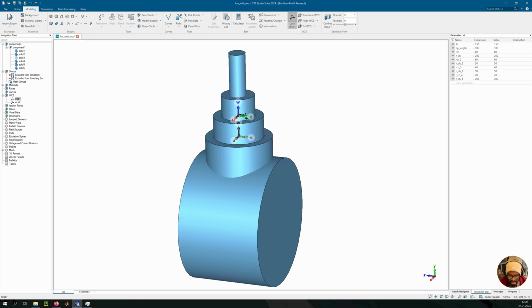So it's starting from the WCS2 because that's the latest world coordinate system, I think. I'll just call it WCS because I'm not sure about the name. So it's starting from the latest WCS because that's the last we used, so it's still recording that as the local coordinate system. Now, in order to get back to previous coordinate systems, this is what I forgot to do: you have to right click and then restore. Then it selects this as the local coordinate system.